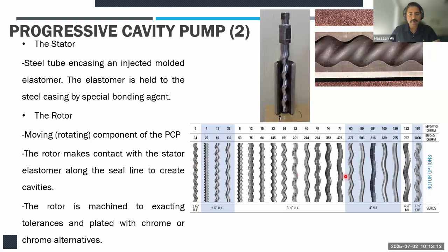So different type of pump models you can see right over here. They go all the way from 2.5-inch tubing to 3.5-inch tubing, suitable for 3.5-inch tubing and 4-inch tubing. You can see different geometries of the rotors, because the different geometries correspond to the different type of fluid rates, different type of solid handling. Some are good for the medium API oil, some are good for the heavy API oil. So you select your geometry based